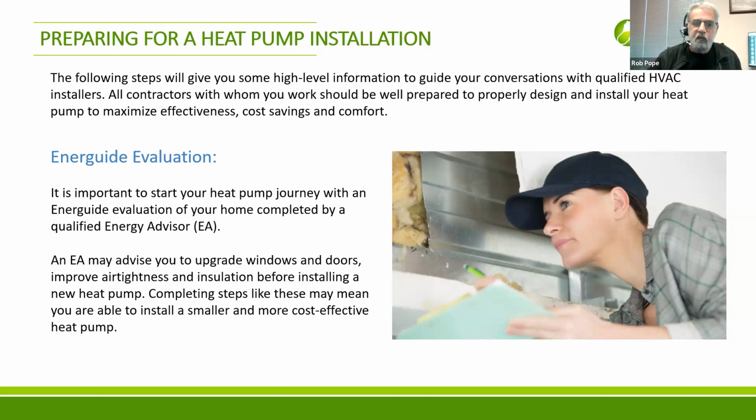They'll also do what's called a Hot 2000 model. All that is modeling the energy performance of the building. What it does is give the homeowner, or whoever wants it, a block load calculation of the heat loss of the building, right? Which then can be used by the contractor to size their equipment.